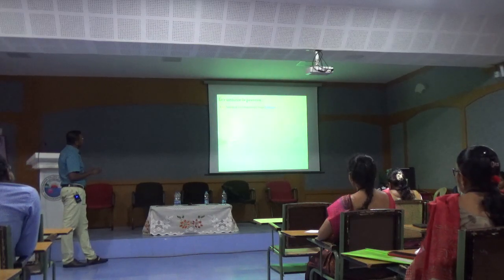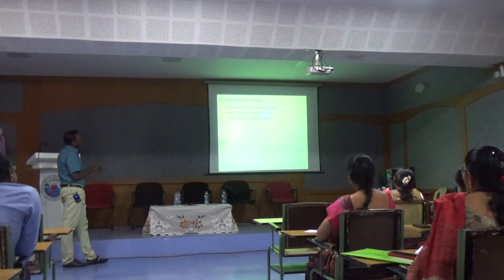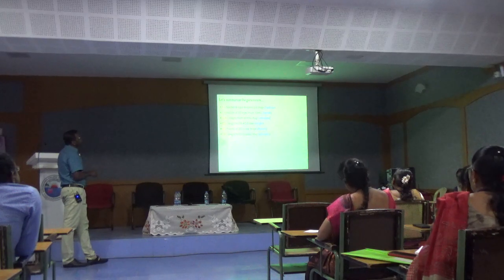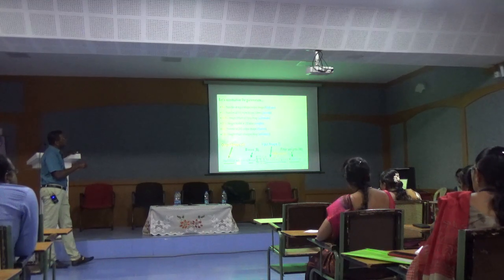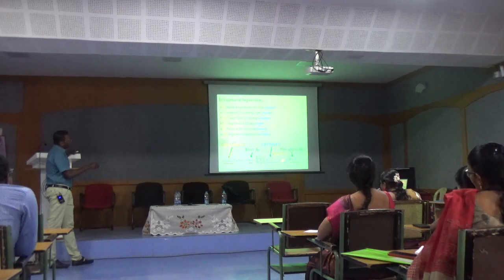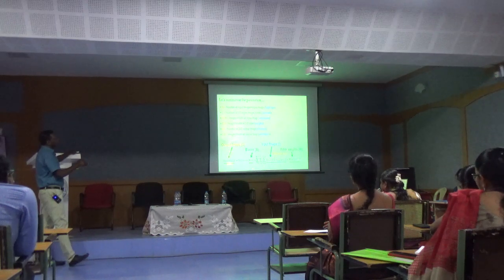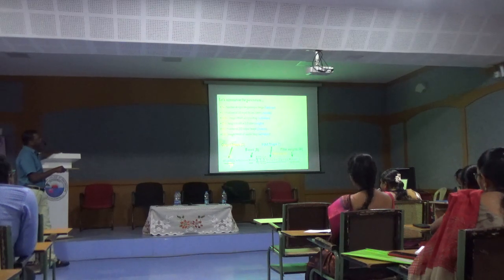So let's summarize the parameters, where N is the number of input feature maps or batch size, C is the number of channels, H and W are the height and width of the activations, R and S are the height and width of the weights, M is the number of output channels, and E and F are the height and width of the output activation. So based on that, we can find out the expression. The output feature map O of M, X, Y is equal to the activation of biases plus input feature map into stride into filter weights. So this will be the final expression for the output feature map. It is the mathematical expression for the output feature map. So from this we will get how many operations are there.